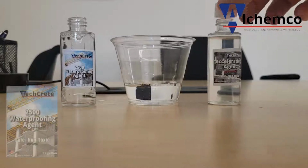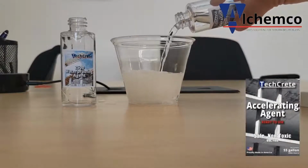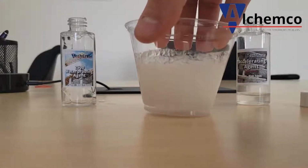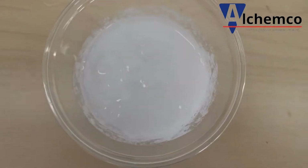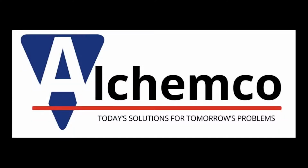So as you can see, it's a clear liquid that we apply. And then as soon as this product is in contact with water and inside the concrete, it's going to form this white gel. So this white gel is exactly what's going to seal the pores, cracks, and capillaries. You don't see that on the surface. So your structure is not going to be white or nothing like that. It's not going to change the appearance, but that's exactly the type of reaction that happens inside the structure.